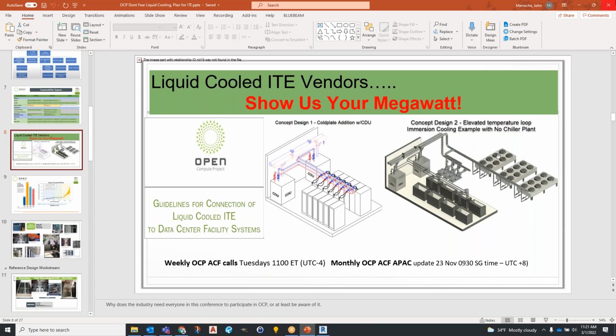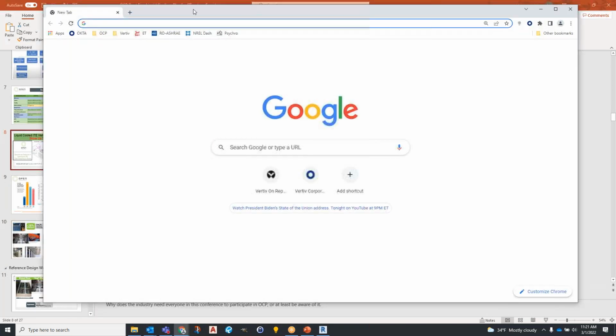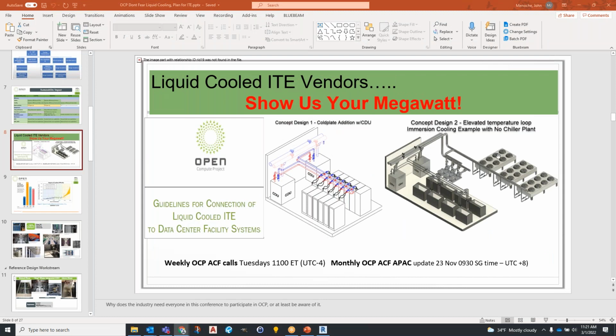For example, I'm working right now with some single phase immersion stuff, and when you look at the weight, the floor loading for the footprint of the actual immersion solution, the wet weight with ITE in it, et cetera, is around 325 to 340 pounds a square foot.